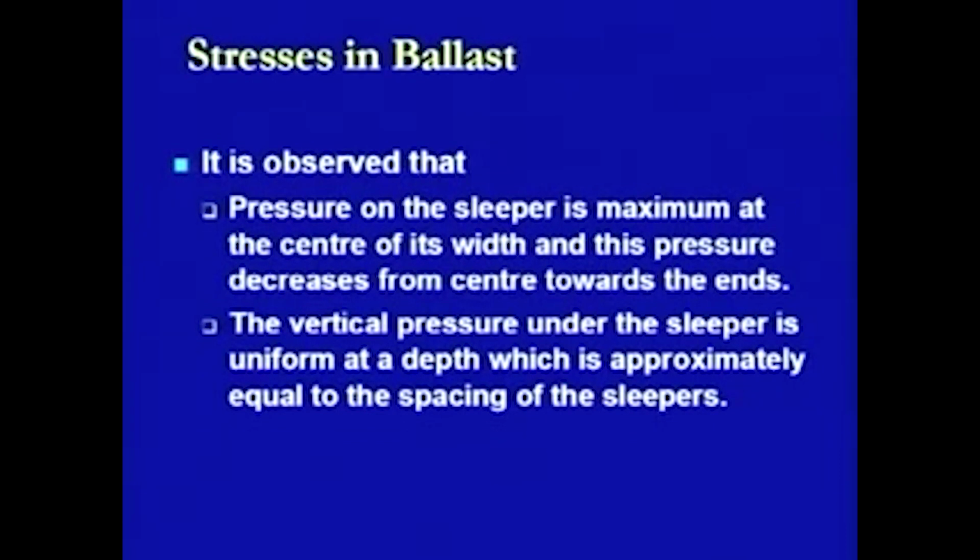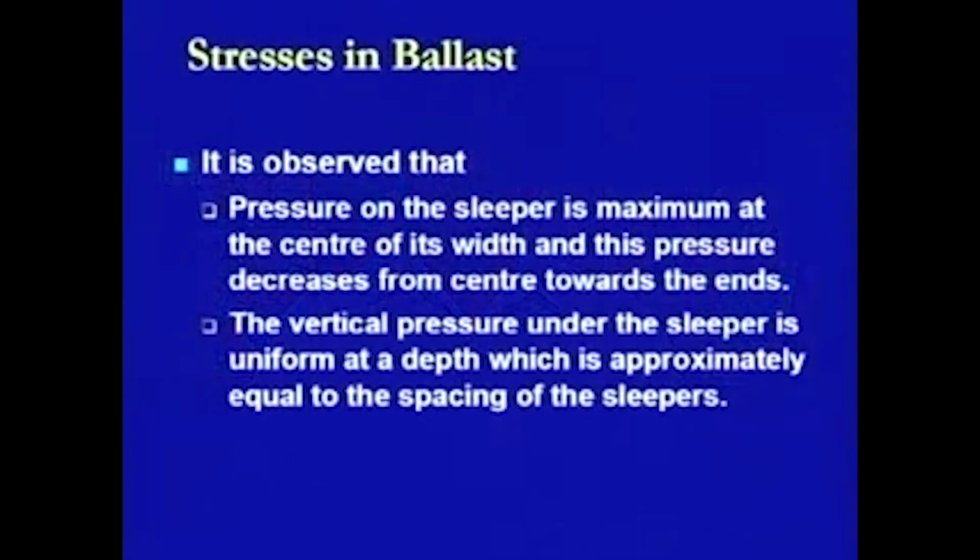What is being observed is that the pressure on the sleeper is maximum at the center of its width, and this pressure decreases from the center towards the ends, and the vertical pressure under the sleeper is uniform at a depth which is approximately equal to the spacing of the sleepers. On the basis of this, we try to observe the stresses which are going to be induced up to a depth equal to the spacing of the sleepers.